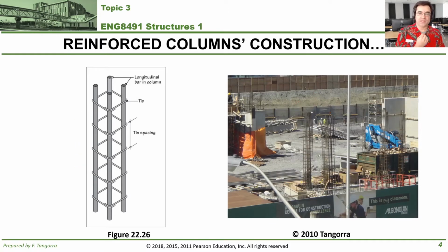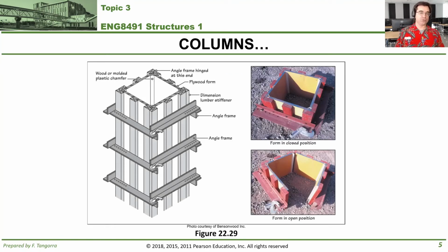So once you've created the reinforcing, you place it on site. Like you see here on the right hand side, you fasten it to the reinforcing of the column below or to a footing and foundation below. Then, as we've learned, because it's concrete, you have to form it.